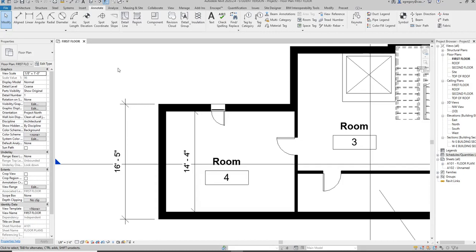But as we move into wall sections and floor plan details, we do want to refine, and so we may not get down to a 32nd of an inch, but a 1/4 of an inch or even an 1/8 of an inch may be appropriate based on what you're detailing.